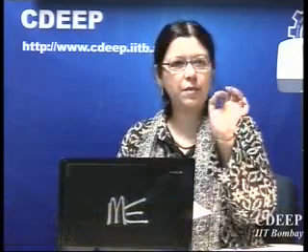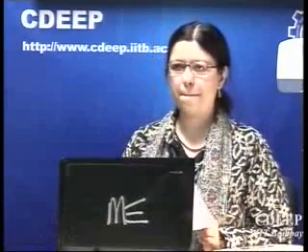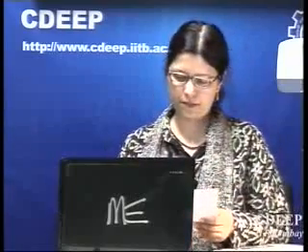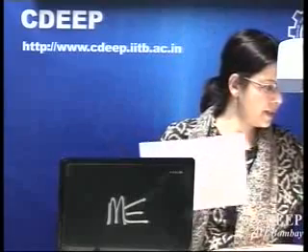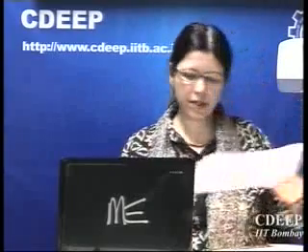Your ADC has multiplied your signal by some gain, but it has not distorted it because all samples are getting scaled by the same value. So eventually you don't have any kind of distortion. That is the reason this offset compensation is very important.